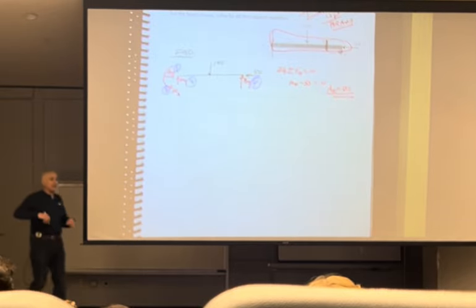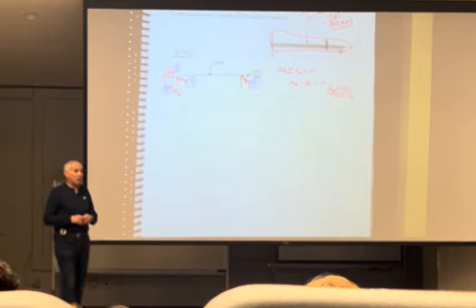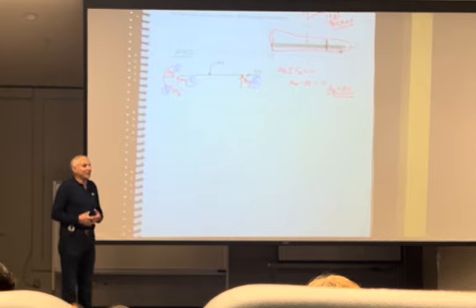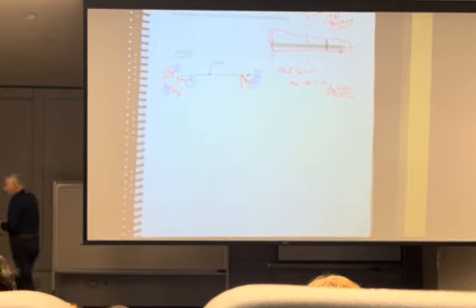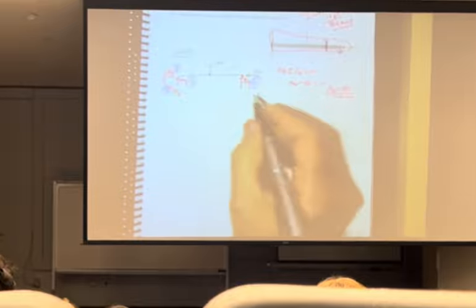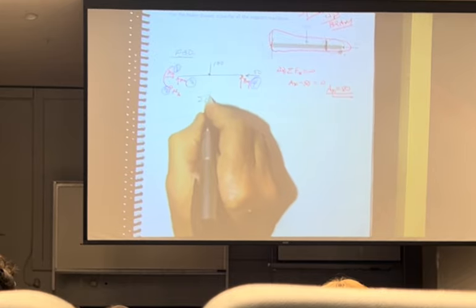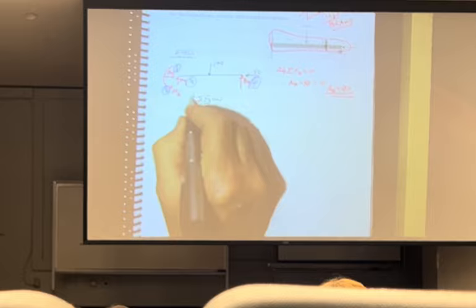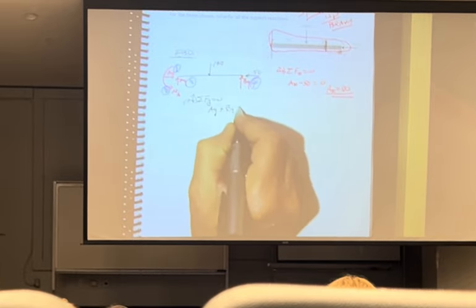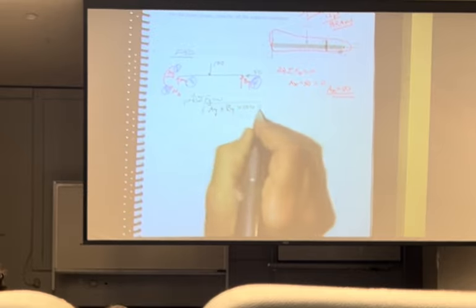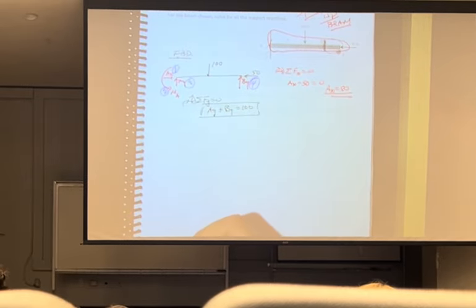So, from statically indeterminate, I can never solve for all the support reactions. I just solve for one of them. If I write the equations, guess what? Sum of forces in the y equals 0, positive upward, says AY plus BY must equal 100. Great, but that's 2 unknowns.